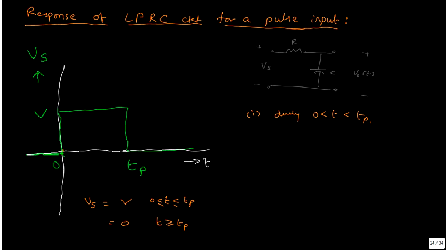That means the capacitor starts rising towards that value exponentially. But whether it reaches that value or not, and how much portion it reaches, depends on the circuit time constant. The circuit time constant depends on the R and C elements of the circuit. So tau is the product of R and C, in seconds.